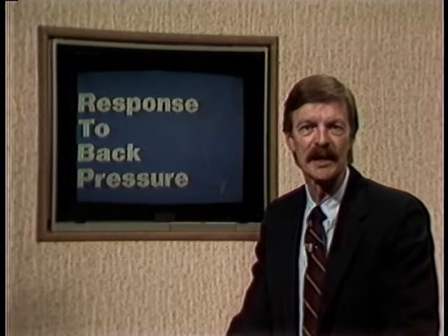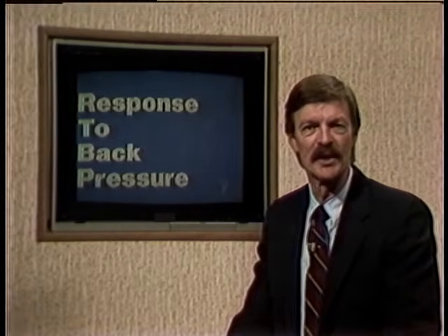Back pressure is the pressure in the condensate line which opposes the supply pressure. It is created by such things as pipe friction, flash steam, differential valves, or receiver relief valve settings, and elevated condensate return lines. For every 2 feet of condensate elevation, approximately 1 pound of back pressure is created. Back pressure reduces the differential pressure across the trap.